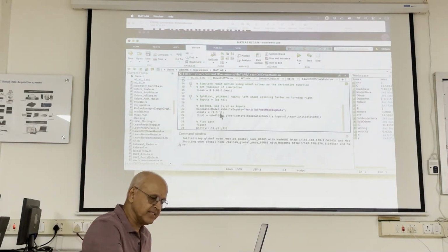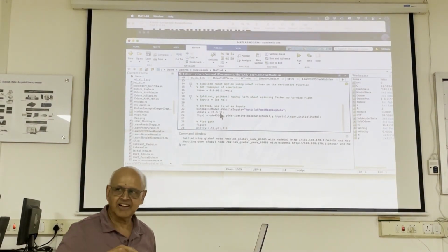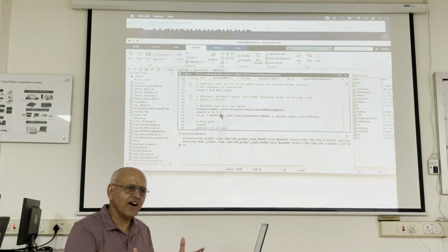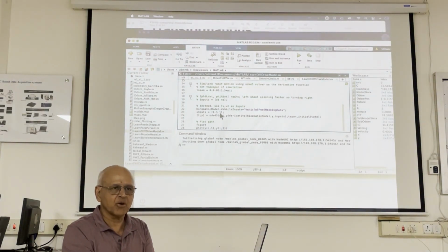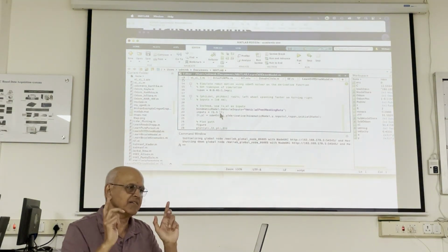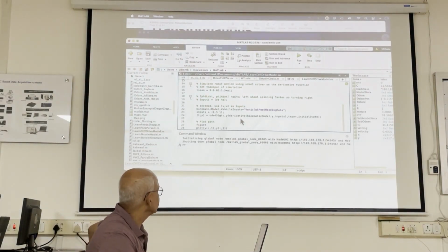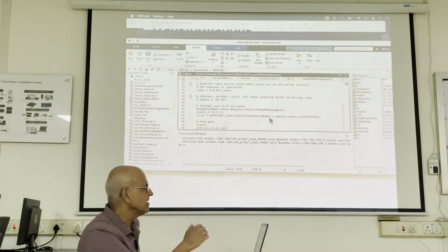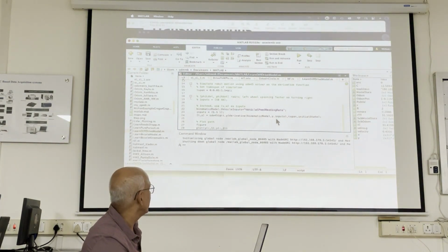And what if I change it point to point? I'll get a very fancy path, won't I? So then you have to numerically integrate. You can't use the equations anymore. Equations are nice for a general understanding, but it's better to differentiate it and let MATLAB integrate it. So that's what is happening here. It's taking the derivative of the kinematic model that we derived, and then it's giving you the result, t versus y. Y contains both the x and y coordinates.